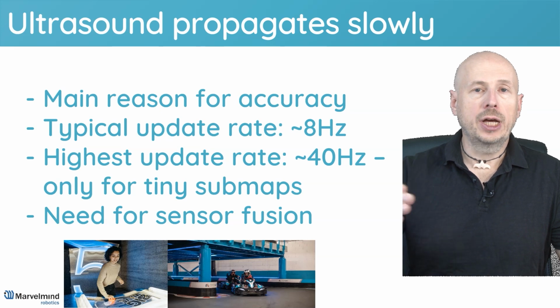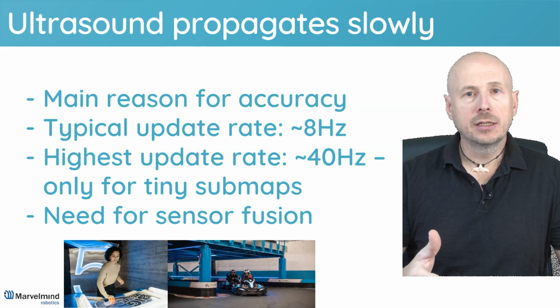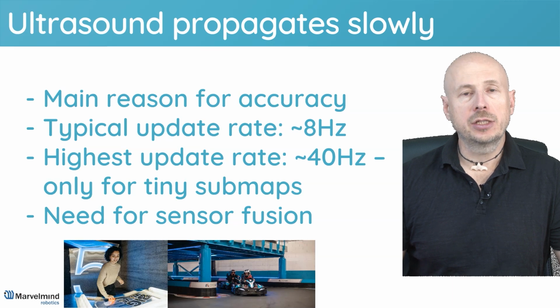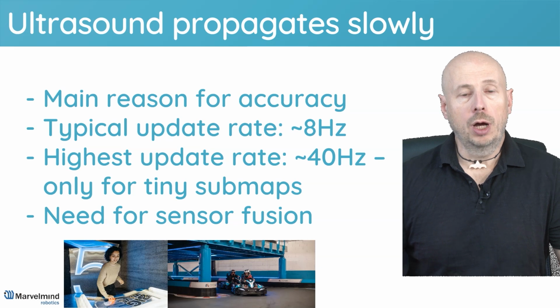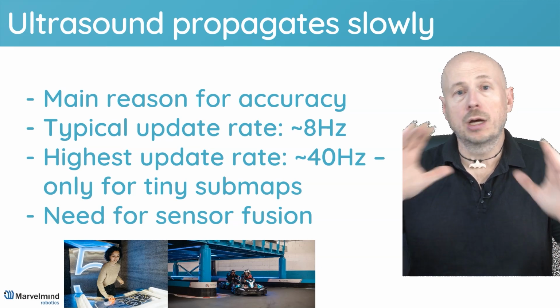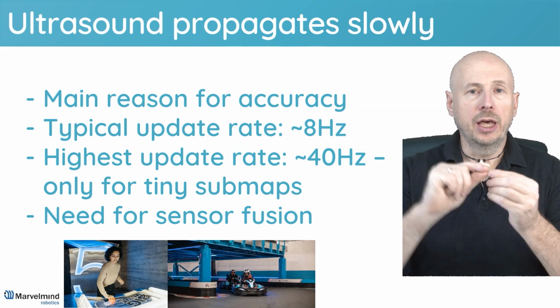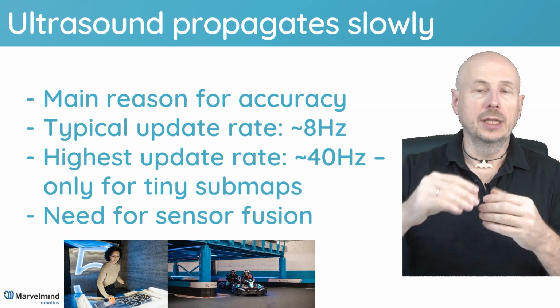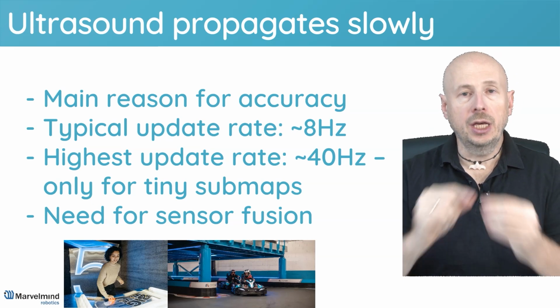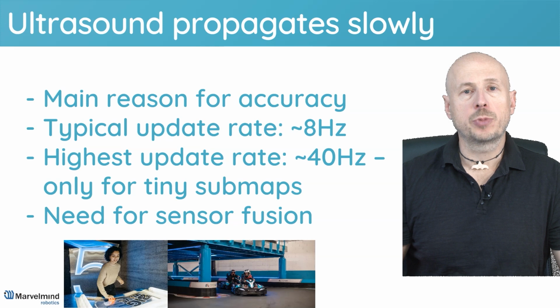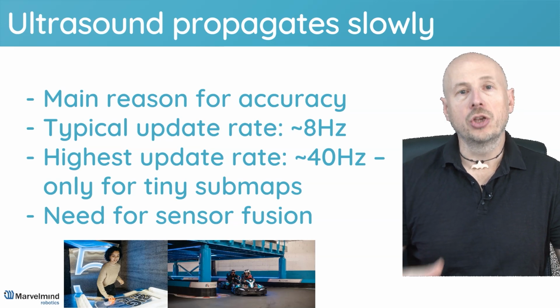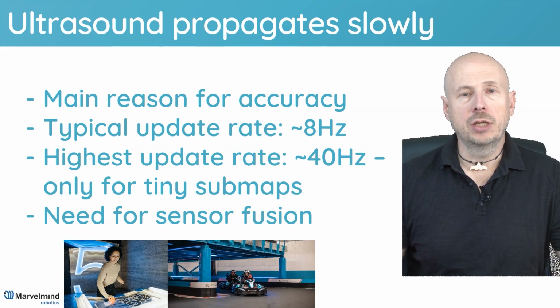So time of flight of ultrasound is the biggest asset when we talk about accuracy, and at the same time it is the biggest limitation when we talk about the update rate. Why? Now imagine that you have a large map, for example, 30 meters. The time for the sound to propagate this distance would be 340 meters per second divided by 30. So a gross maximum update rate that you can achieve without any other time losses would be around 11 Hertz, which